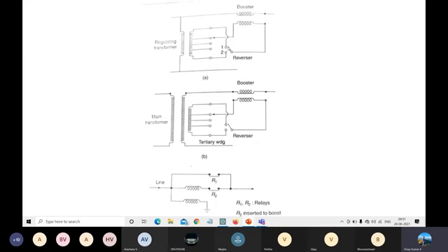And if you are interested to decrease the voltage levels, then change the polarity of the booster transformers from first position to second position by reversing the reverse switch. Then we can use that as a buck transformer.